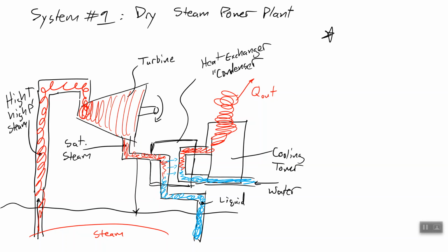because the condenser turns steam, which takes up a lot of volume per unit mass, into liquid, which doesn't take up very much volume per unit mass. Imagine how much steam you would get from evaporating a little bit of water. So that really decreases the amount of volume this water is taking up, and it creates a suction effect that's pulling more steam through.